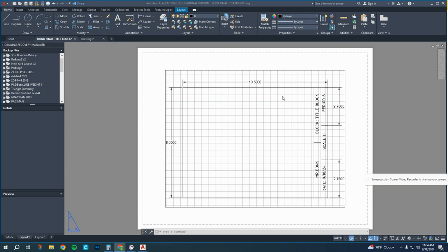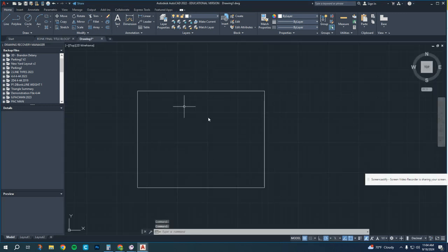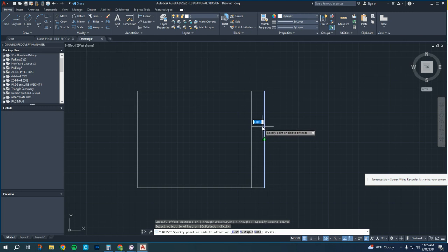That's okay. What we're going to do is draw in or place in these boxes and divisions of boxes, and that's going to be using an offset command. So what we'll do is click this offset tool, and you're going to click on this line on the right side here. It's going to take 3 times to start to do an offset. An offset is a copy of something exactly parallel to it. An offset could be curved or a straight line. In this case, we need a 1/2 inch offset.